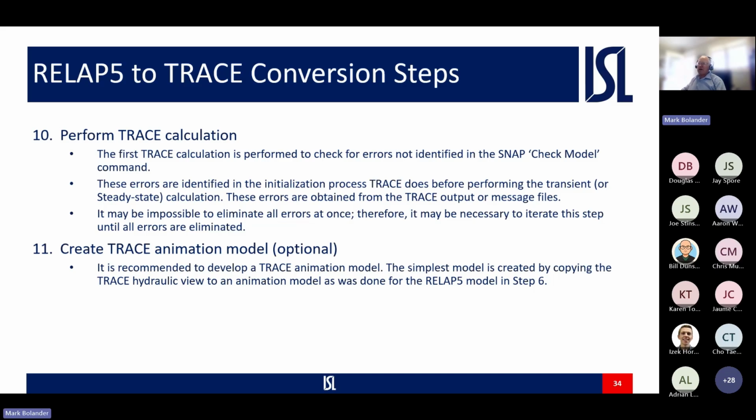And then once you feel satisfied that you've got your errors fixed, go ahead and run your TRACE calculation. More often than not, you're going to have some more errors that TRACE is going to point out, so you're going to have to iterate on this step until all of your errors are eliminated.